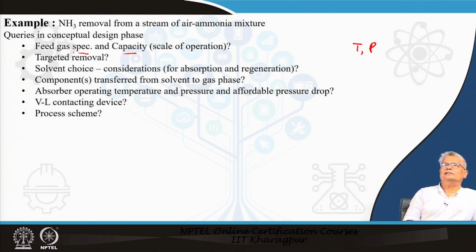It is also obvious that we have said earlier that while contacting, it is inevitable that some amount of the solvent component will be going to your gas phase. For example, if I have cold water which is being used as solvent at a temperature of around 25-30 degrees centigrade, and my feed gas is at a temperature of around 40 degrees centigrade, what is expected to happen is some amount of water would definitely vaporize from the solvent phase or the liquid phase and go out along with the gas which is treated.